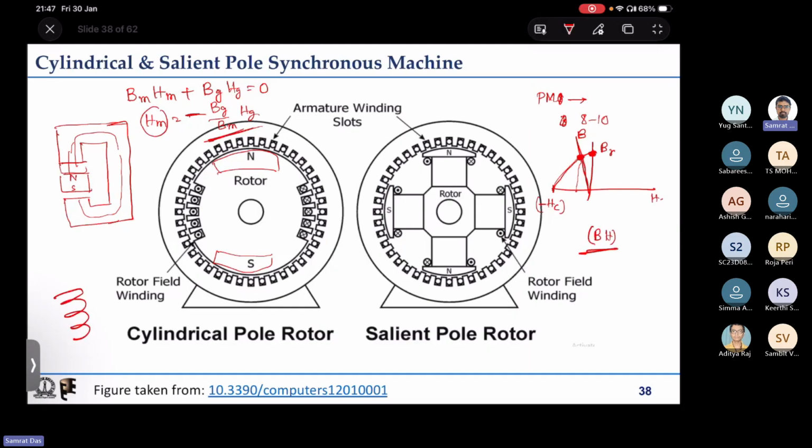that means we have some coil and some air gap. The energy density that the coil can produce is W equals 1 by 2 mu naught into B square. So for a given air gap, what is the flux density that it can create? This number gives the energy density produced by an electromagnet. Now suppose it wants to create the same B field. You will require a lot of turns and a lot of current, and currents will also have some losses, so thermal things have to be taken care of.